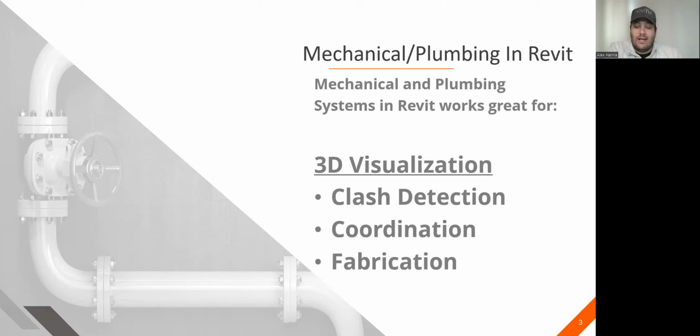So you get advanced coordination, clash detection, and you can do fabricatable models from it as well, because now you can rotate that piece in any way that you want and be able to diagnose which piece is A, B, C, D. I will touch on the 3D visualization once we do more of the demo later, but understand the 3D model and clash detection is highly important because you can now move around the space and see why it's clashing and where it is.